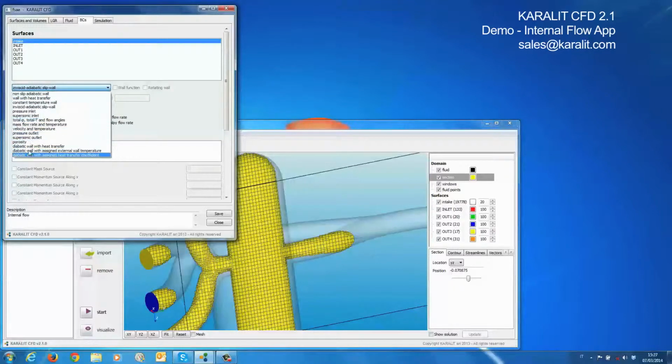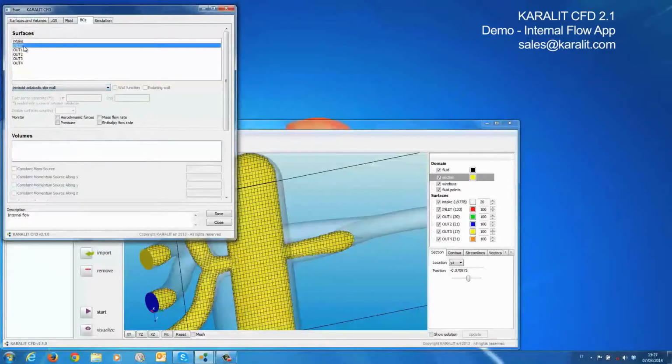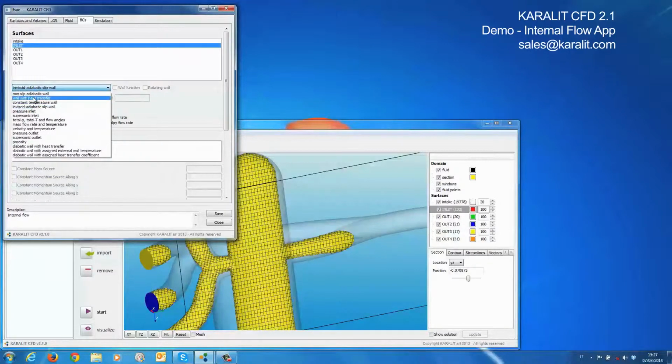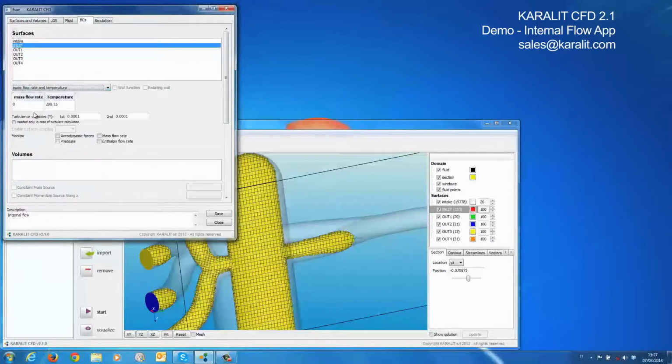We can do different kinds of characterization of the wall, of the surfaces, even a thermal characterization, porosity, and things like that. The inlet is going to be a mass flow rate inlet of 0.07 kilograms per second. And I'm going to monitor both pressure and mass flow rate. Even if mass flow rate is imposed, we can just use the monitor to check.